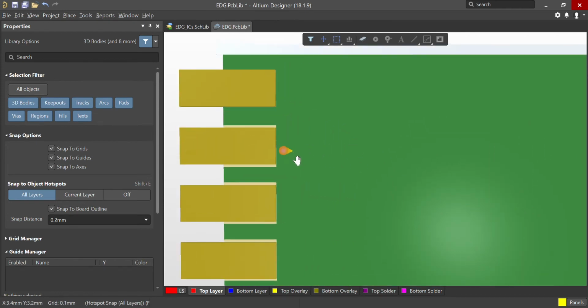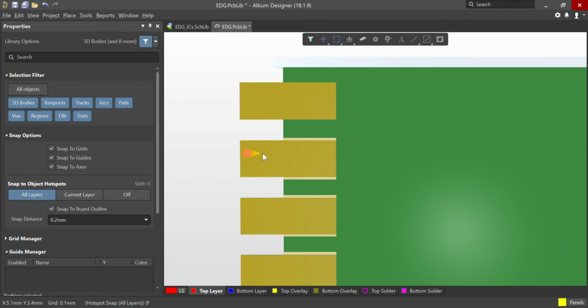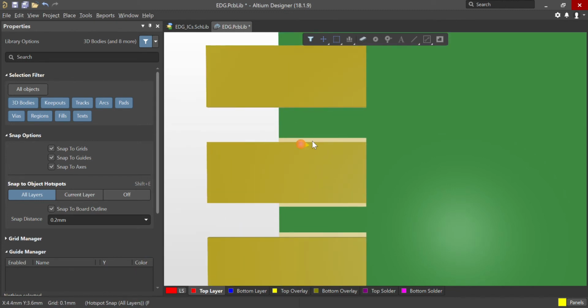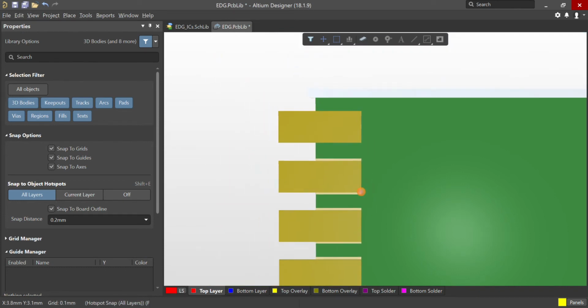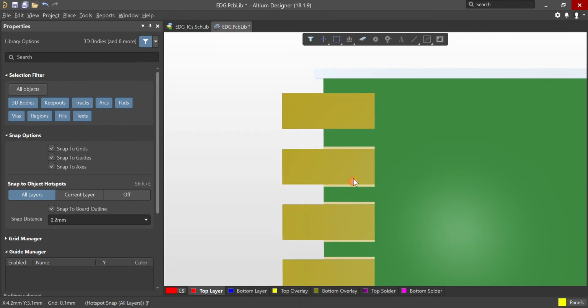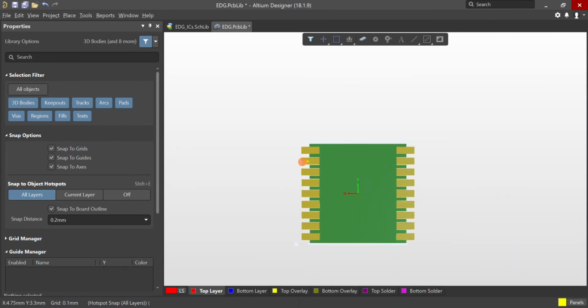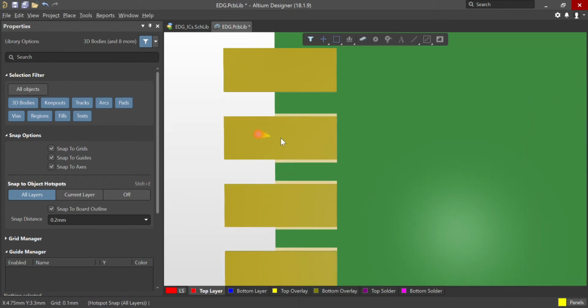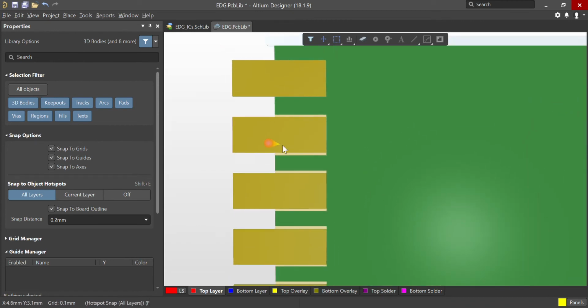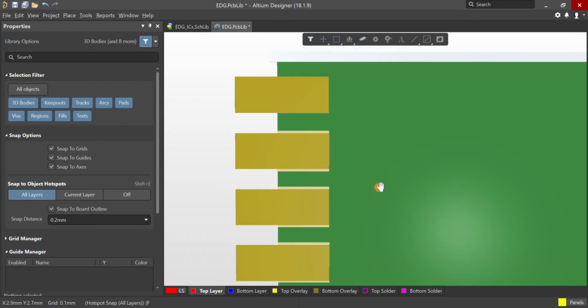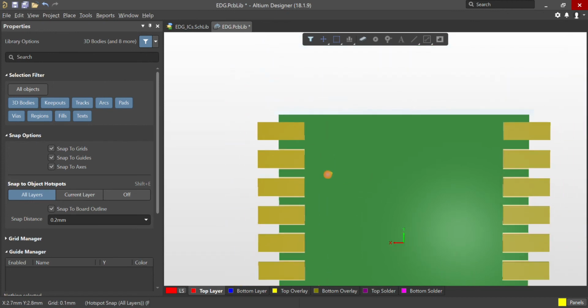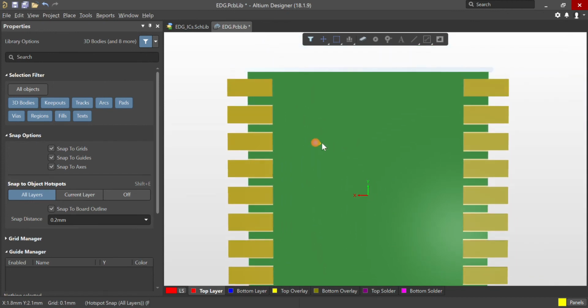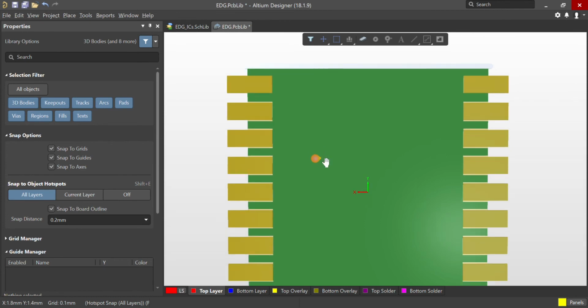You can actually see that all of my pads I had created the same size, but on the bottom of the part, I've noticed here that the copper is a little bit wider than my pads. And I checked the data sheet, and it actually turns out that all of the pads that are not these ones on the edges, they are indeed a little bit wider than what I've drawn them at. So, this is a great way to not just make your design look better, but it's a great way to catch different types of errors.